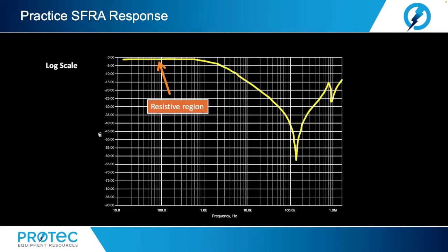A low-frequency effect where there is a resistance which prevents the coil having a 0 dB response at low frequencies. A high-frequency effect where turn-to-turn capacitance counteracts the continued roll-off of the inductance.